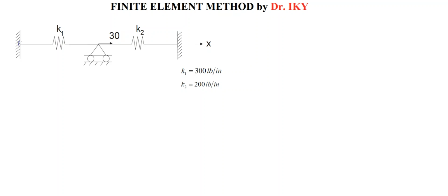If I want to create an application, this one, for example, will be the first node. Here we have got the second node, and finally the third node. Again you have got one axis, which means you have got the x, and we will have deformation or displacement systems. So I want to define the elements with the rectangular definition. This is the second element. And we know that K1, K2 are the stiffness matrices.